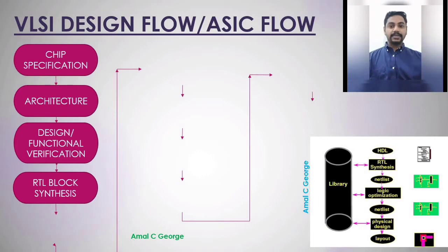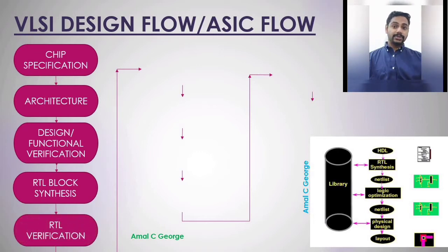So, the next step in the design is RTL verification. This step ensures that the design is logically correct without any major timing errors. It also eliminates all syntax errors from your VHDL code. System Verilog and UVM test benches analyze the code by giving binary values.